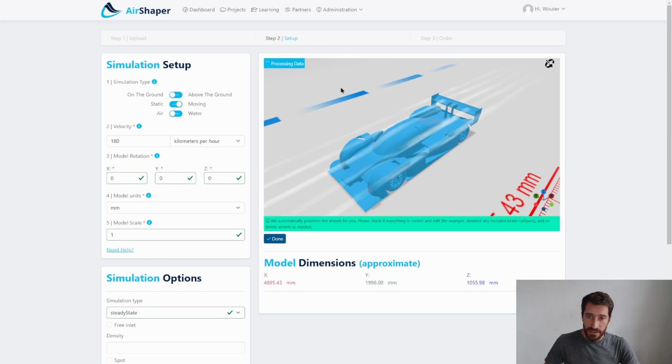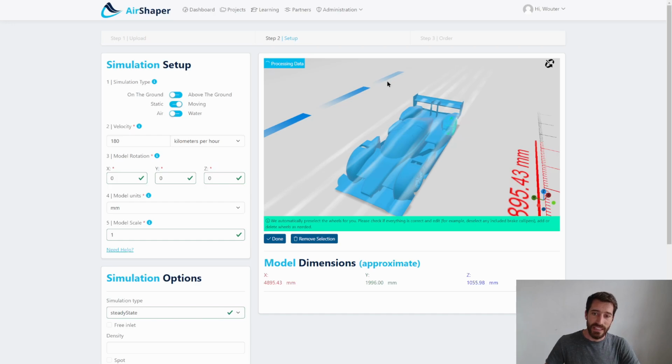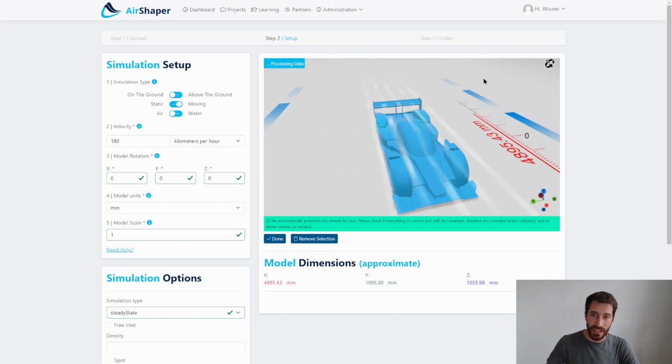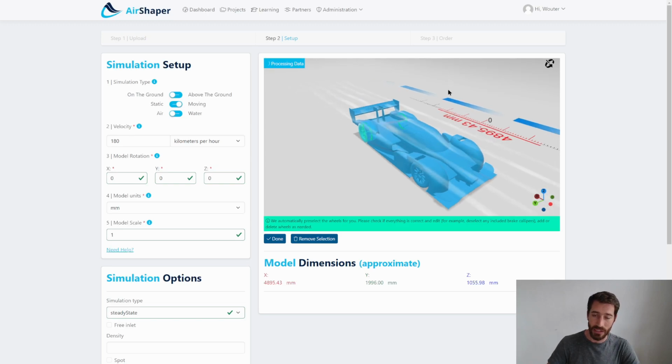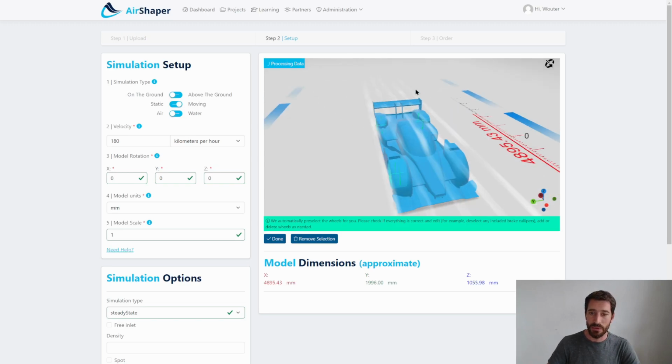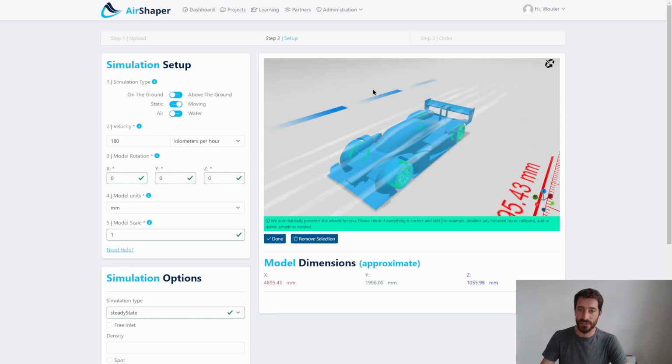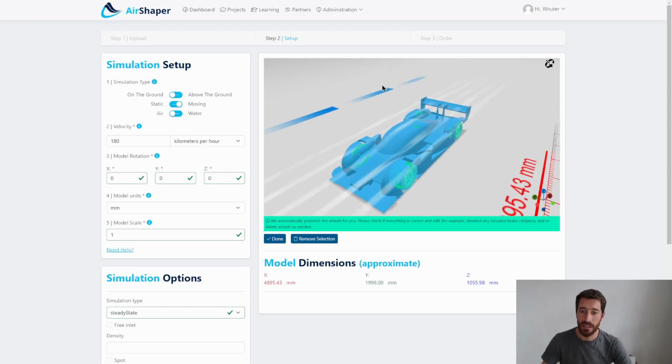And once your simulation has been set up, we have this interface that will automatically detect the rotating wheels on a car. So even though this is a, with all due respect, dumb STL file, which doesn't contain intelligence like a radius or a distance or anything, we automatically detect which parts are wheels, and we will automatically find the central axis of rotation of a wheel, and we will apply a rotational velocity which matches the forward driving speed of the car via the radius of the wheels.